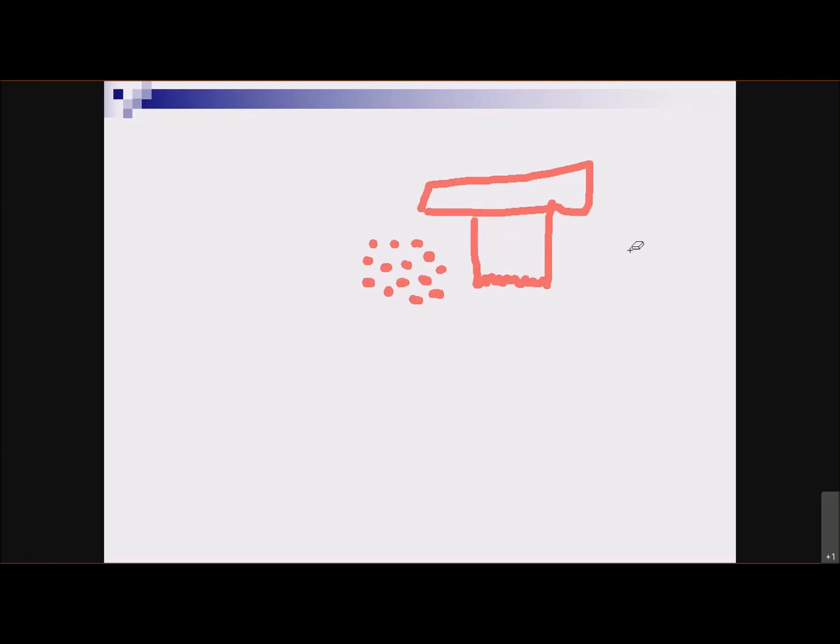So the nice thing about this, why this works so well, is that not only does it account for the volume of air coming in, because more air coming through, like if you open the throttle, means more molecules of air hitting that sensor, but it also accounts for the density.